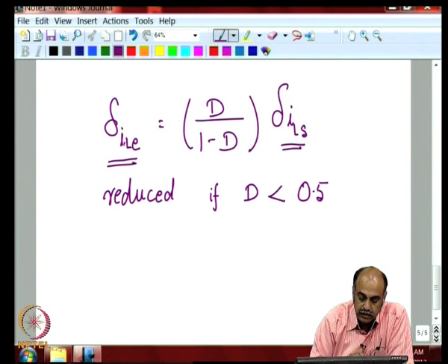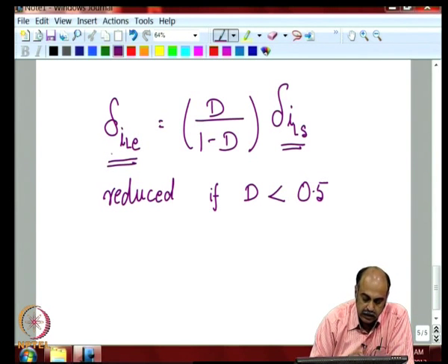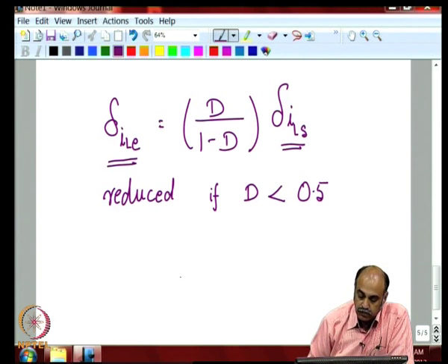This becomes the perturbance for the start of the next period, which will further reduce in the following period, and so on. It will asymptotically reduce till the perturbance is rejected. Therefore, we say for all duty cycles less than 0.5, the system is stable.